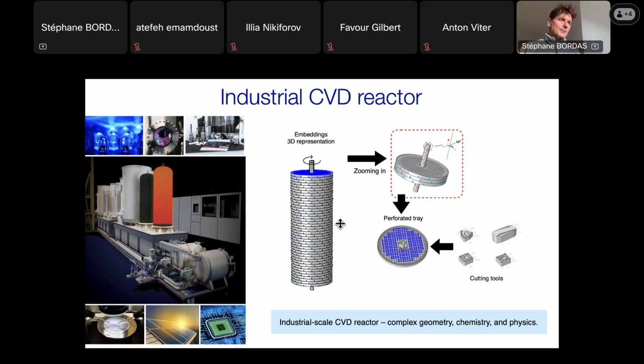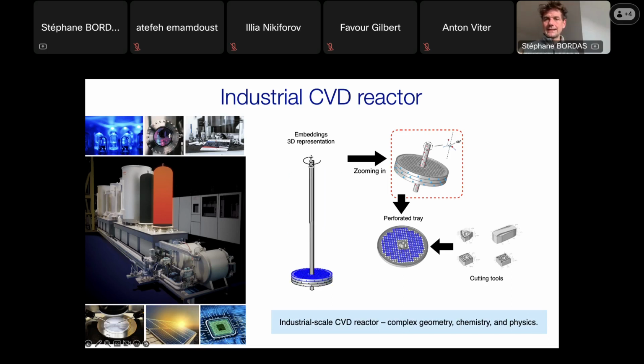And the problem, obviously, maybe obviously, I don't know, is that if you blow whatever chemical vapor from the bottom and you move up the cylinder, you can imagine that the conditions in terms of pressure, velocity, and concentration of these species is going to vary along the height. So it may be that at the bottom you have a higher concentration, at the top you have a lower concentration because there was already deposition.